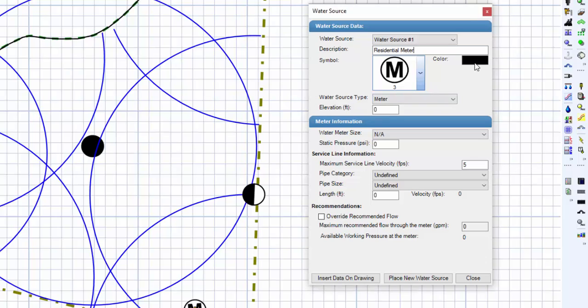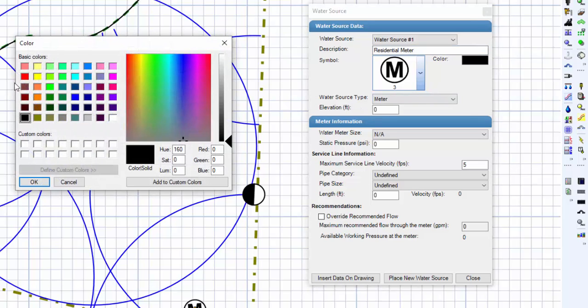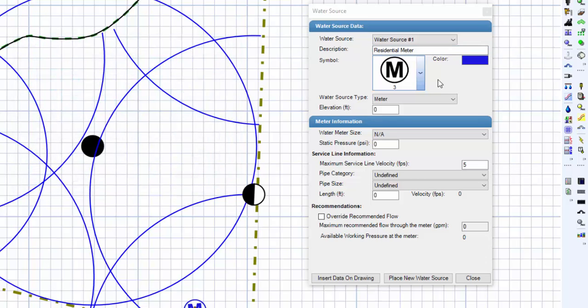To choose a color, click on a predefined color of your choice, click somewhere inside the color box, or move the slider bar to select the color assignment. You may also enter the red, green, and blue values in the associated text boxes. Once you've determined the color, click on the OK button to accept the color assignment.